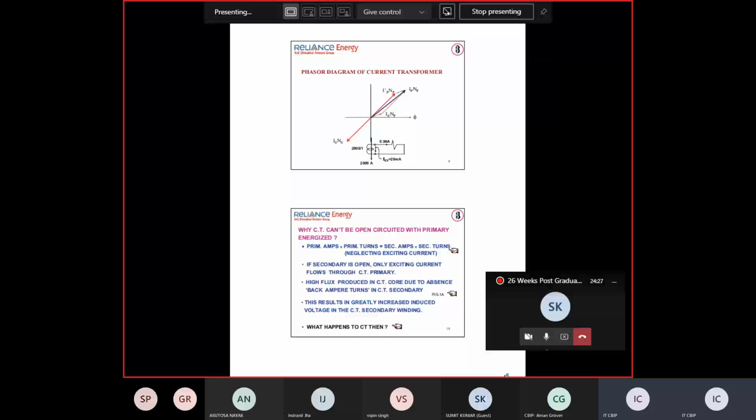Right? So, 66 kV, there is a defined relationship and concept I will convey. This housing model is a 5 bay. You did the 5 bay exercise, right? 2 number sub-transmission lines of 66 kV, 2 number trafo bays 66 by 11 and with a 20 to 25 MVA rating.